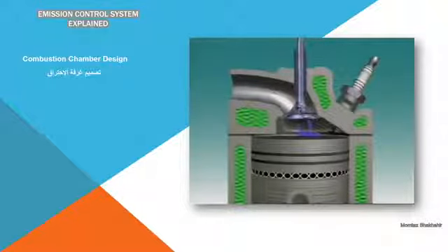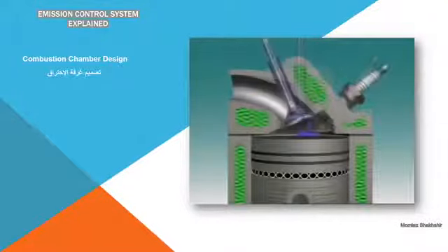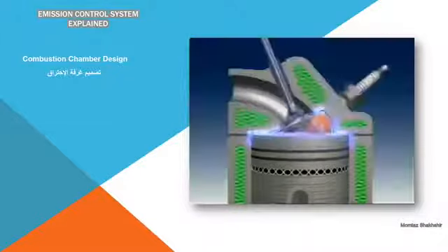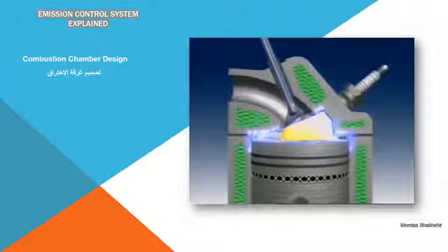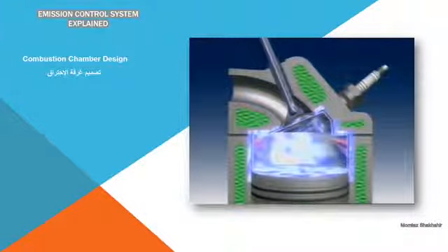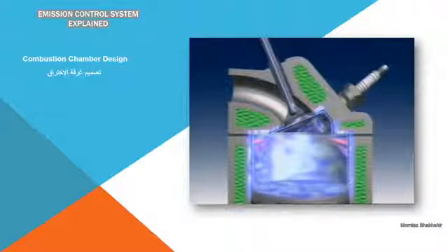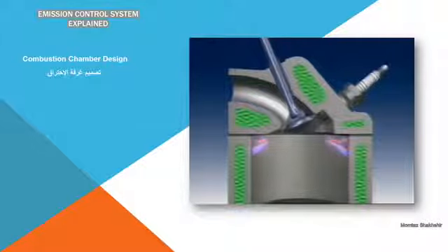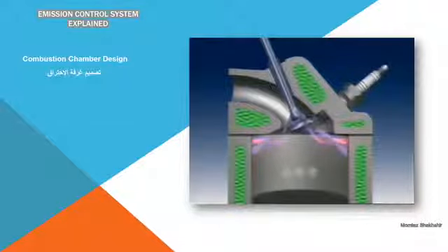Combustion chamber design can affect the combustion process also, and therefore the level of emissions. Designs that increase gas flow rate and promote vaporization distribute the fuel more evenly in the combustion chamber. Quenching of the combustion flame can occur in zones in the combustion chamber where surface temperatures are low. The flame temperature drops so low in these areas that the flame goes out or is quenched. Fuel left unburned in these zones is then exhausted as hydrocarbon and carbon monoxide emissions.